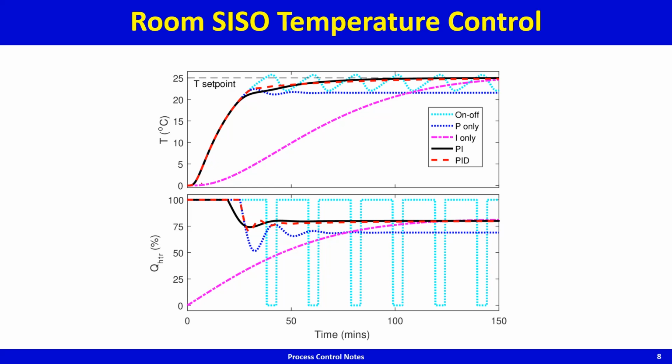In response to that heater duty going to maximum, temperature starts to rise. It exceeds T set point, and as it exceeds T set point plus delta, the heater is switched off. The temperature continues to rise before turning back around, and then it goes below T set point minus delta. I think I used a delta value of 0.5 degrees Celsius. I don't remember exactly.